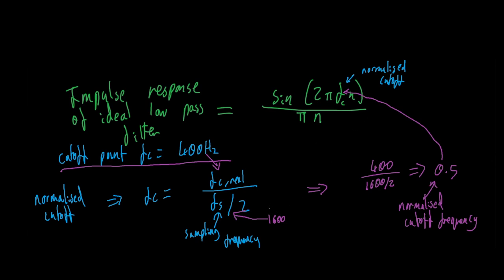And that's the point. If the sampling frequency changes, FC is not 0.5 to filter out 400 anymore. It will be different based on this ratio here. You need Fs, the sampling frequency, to be 2 times the max frequency present in your signal. So let's take this sine wave here. You have one sine wave cycle, that's in time and amplitude. For your computer to recognize this is a sine wave of a certain frequency, it has to be able to sample it twice. So that could be one here, one here. It could alternatively be here or here. The point is it has to be able to sample it twice per sine wave's cycle.